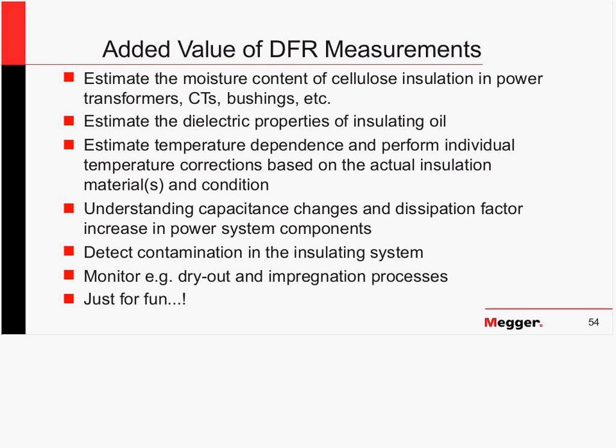insulation. It's not just for transformers. You can do this on instrument transformers, CTs, and bushings as well. We estimate the dielectric properties of the insulating oil, the temperature dependency, and then can use it as a tool to understand capacitance changes, power factor changes in a traditional power factor test. It could be used to monitor dry out processes and impregnation processes.